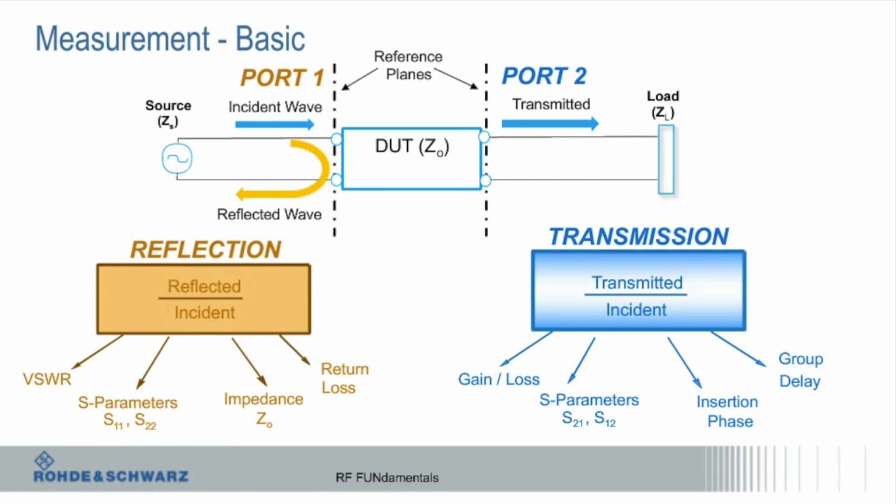Anyways, all these other things we can measure with the VNA. Again, when I do a calibration, I'm going to establish my measurement plane at these two ports, right? That's establishing a phase of 0 and an amplitude reference of 1. So anything I put between those two things is what I measure. That's a pretty cool thing that's unique. So we can measure phase, insertion phase, that's the phase response through here. Group delay, return loss, whatever. Impedance, things like that.